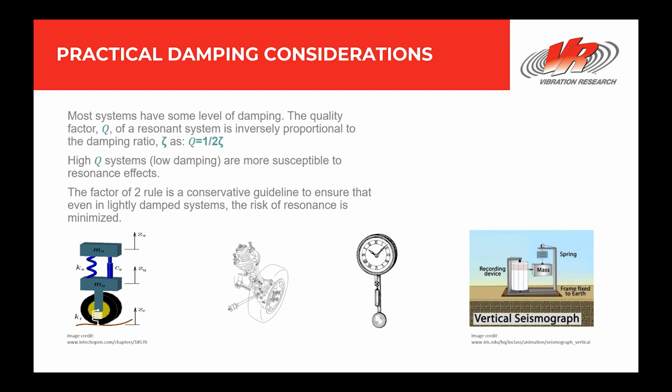And thirdly, the third example would be a seismograph mechanism. Instruments used to measure earth tremors or vibrations are often overdamped to avoid oscillations that could distort the measurements. The overdamped mechanism ensures the recording needle returns to its original position slowly and without oscillation.